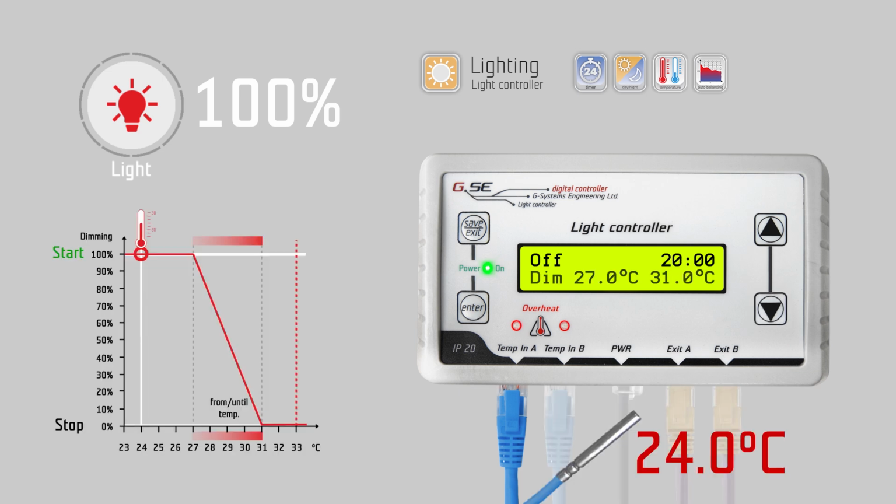Dim from temperature, is the lowest temperature value to start the dimming. For example, we set this to 25 degrees Celsius. Dim to temperature, is the greatest temperature value with the lowest dimming. For example, we set this to 29 degrees Celsius.